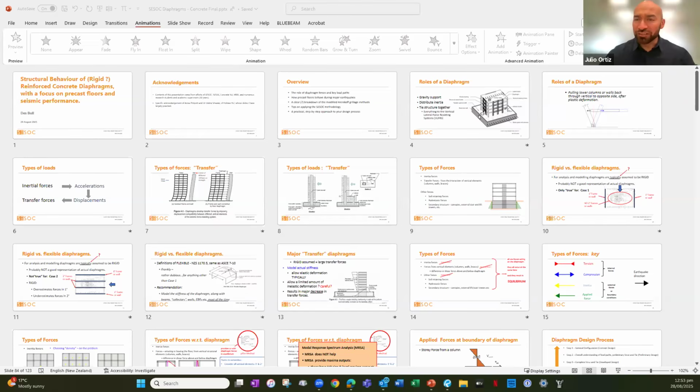Now, the next one, I think you talk a little bit about this: how do you handle vertical steps in the diaphragms? For example, in an old building, they somehow have a 300 millimeter step between the balcony and the internal slab. And just to clarify, this is a DSA situation, so we don't have the opportunity to locally thicken the slab edge like you show in the slides. You simply delete the struts and ties in the grillage model? Is there a better way?